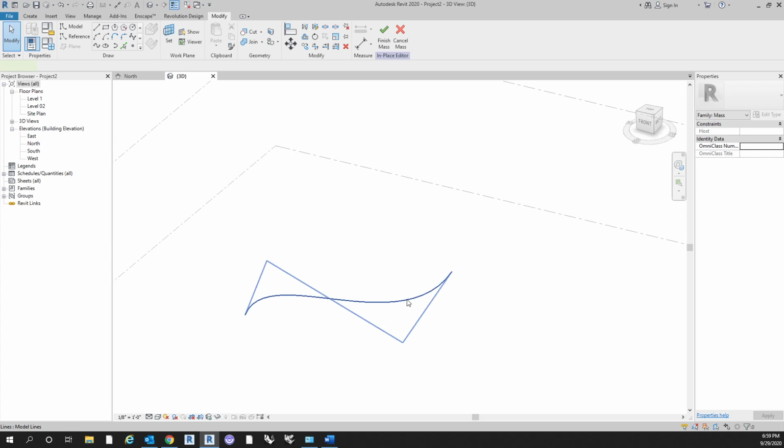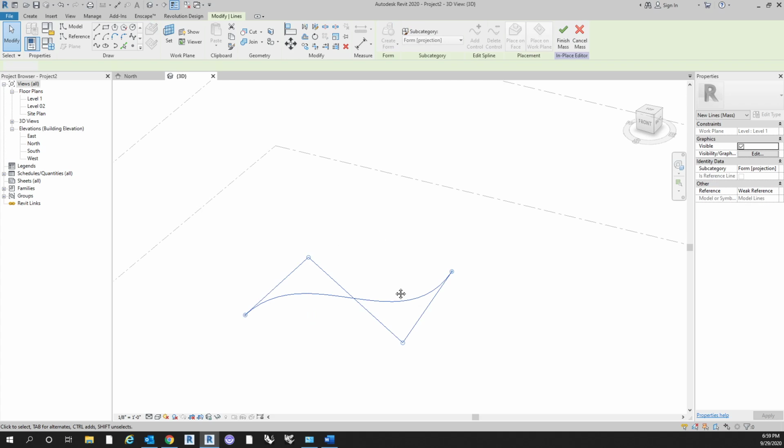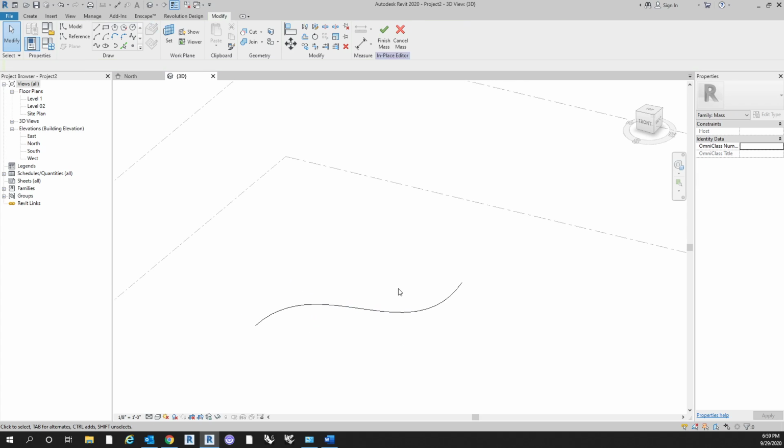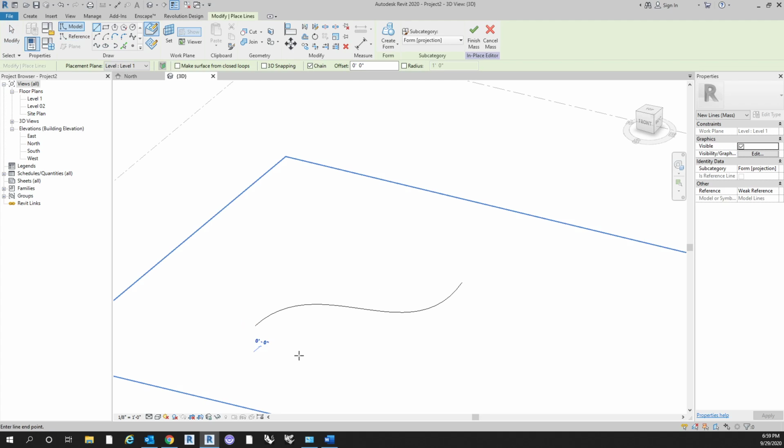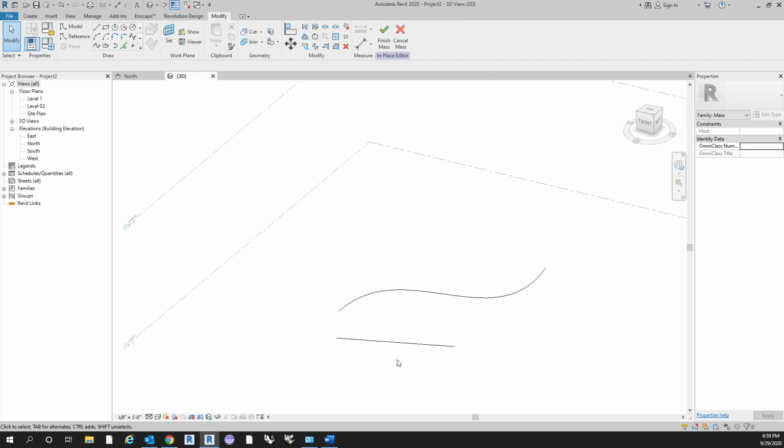They're okay. Obviously, we'll use them today to create some more complex double curved surfaces, but they're a little tricky. There's a couple reasons why. One is that, if we drew another line and we tried to trim or extend to that curve, it's not going to do it. If we did it in Rhino, it would assume a certain tangent coming off this endpoint. It would trim or it would extend it out and meet that other line. But in Revit, it's just not set up to be able to be manipulated.